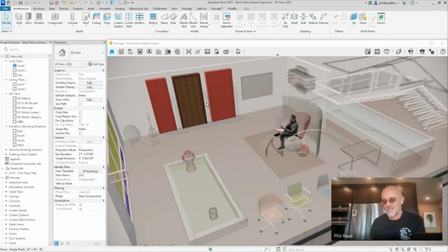And what Scott's thinking behind this when we were chatting was, hey, sometimes things need to change colors and alert you, not based on a specific value that you assign to it, but based on a rule that you've created. So in this case, we're saying, show me anything where the door is less than 24 inches and show me anything where the door is more than 36 inches. Just light it up. And you can keep the exception if you need, but if you just want to find them.